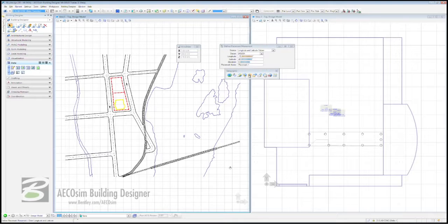We're going to click on this icon, 5th in from the left, 6th from the right, and you can see straight away that we have a source up at the top here. We want to click that and say Reference with Geographic Coordinate System. This changes the dialog box, and now we need to click on the jump box into Reference and select our C underbar Site 2D. We can also give it a fancy name, but Placemark 1 will suit our needs exactly